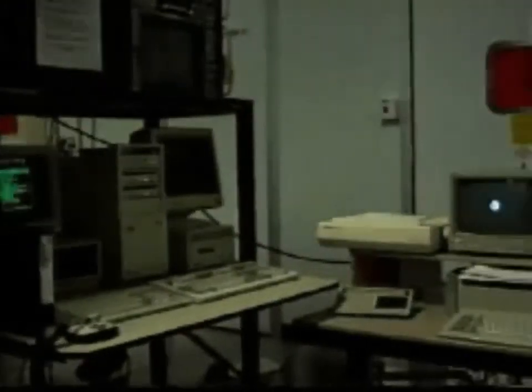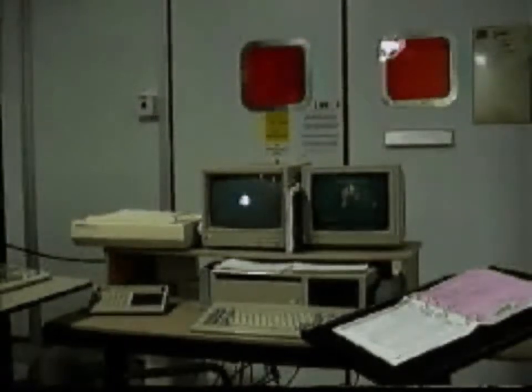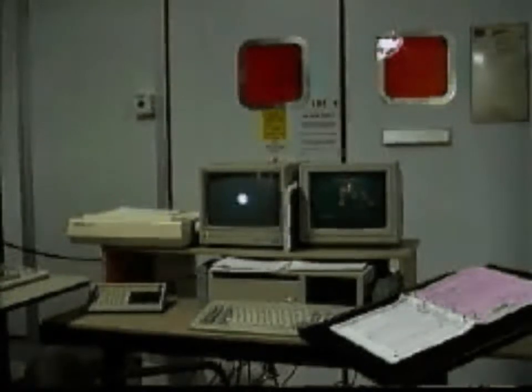The most common input format is the so-called gold disc, the CD recordable disc. When we receive this into the factory, we log it onto the computer system so that we know where the data is in the factory, and then we examine the data to make sure that it is of the correct format and that we can read the disc satisfactorily. If the disc can be read okay, we then proceed to master the disc by feeding it through the mastering system, which is used to modulate a laser beam on our laser beam recorder, which burns the pattern of the data into the photoresist layer on a glass master.